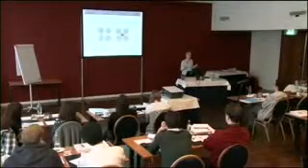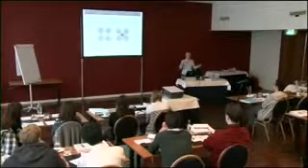At a certain time, it seemed that the porosity repercolated, became connected again, the larger porosity, and maybe due to microcracking. But that means that the way you cure the sample has an impact on the porosity you get, even though if you were just modeling this, it would be the same system.